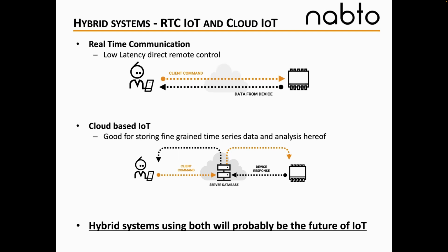So in a CCTV camera application, some of the surveillance cameras also have limited memory. And if you have limited memory, it's going to be a limitation with WebRTC, because you have to use some of the built-in APIs that come with WebRTC, and they require megabytes of memory. So that's one limitation. At least today, we cannot go down to kilobytes of memory. Of course, there's also some CPU, but the most limiting factor today is memory. So doing WebRTC, you need, I would say, at least something like 10 to 20 megabytes of memory. Oh, okay.